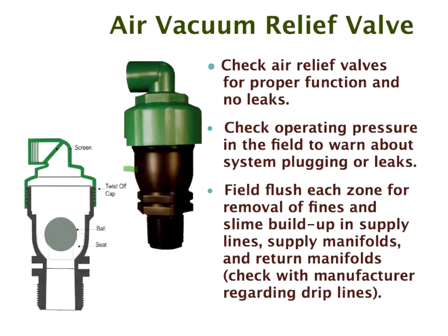Again, we like this one because if you want to flush the manifolds, you can unscrew this part, take it off, take out the ball, screw this back on, and then screw a hose on there, switch on the system, and take the flush through a hose to wherever you want, into a drum, or back to the pump tank or the treatment plant if you're close enough, and flush out the manifolds.